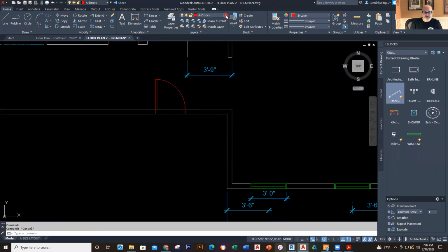So once I've got that in place, let me just go ahead and make sure that it's in the right place. I'll go ahead and go here, over to here, and that tells me that that is indeed 3'6". Let me make sure it actually is 3 feet. I'm not sure it is. Here to here, is it 3 feet? No, it's 2'6". So I'll click on this, and I actually need to pull this over to 3 feet. Okay, and then I need to move it over 6 inches because I placed it. I didn't make it as wide as I should have. So it's 3'6", and then I trim out the information that's in there.